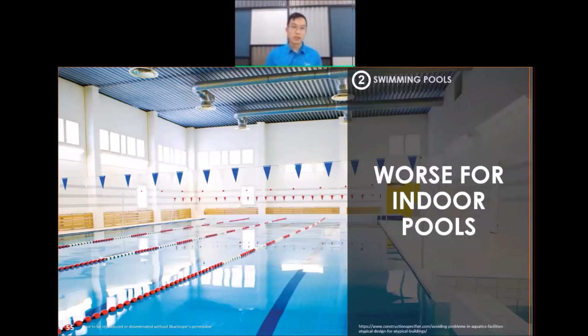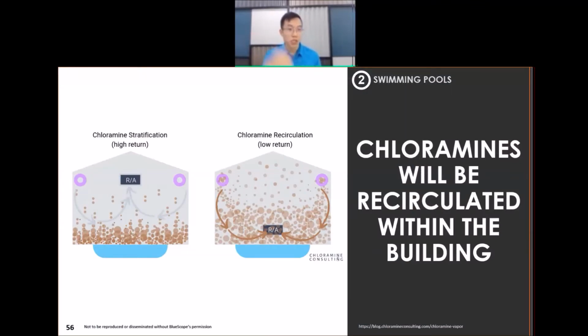How an indoor pool makes it worse is that when chloramine is generated as people jump into the pool, it will not be able to escape freely by natural ventilation. And in fact, if there is any indoor HVAC system, there is a potential of this chloramine being recirculated into the building as well.